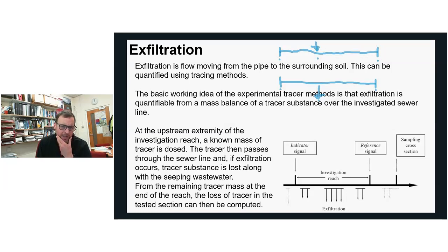So this means you can't use that kind of test, but what you can do is measure the flow rate here and the flow rate there, or also measure the dye concentrations, and work out the total mass of the dye, or a total volume of dye. That's what's happening in this text here, to describe how you can identify exfiltration. So it's a little bit more complex, and you do need much more accurate equipment, I think.